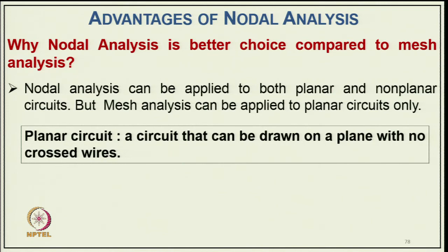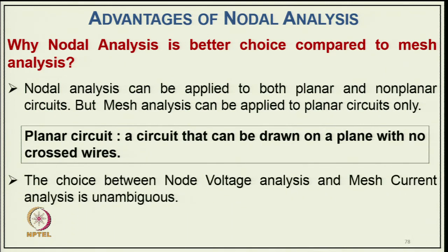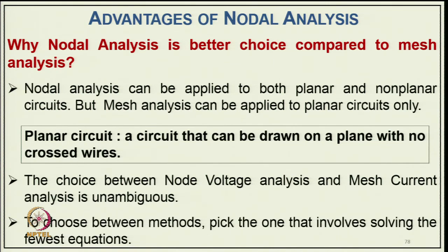Nodal analysis is a better choice compared to mesh analysis, since nodal analysis can be applied to both planar and non-planar circuits, but mesh analysis can be applied only to planar circuits. A planar circuit is a circuit that can be drawn on a plane with no crossing wires. To choose between node voltage analysis and mesh current analysis, pick the one that involves solving the fewest equations.